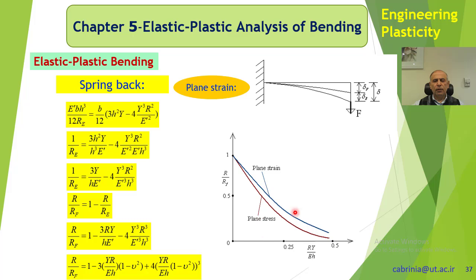Okay, so that is the difference between plane strain and plane stress, but this difference, in my opinion, is not important, because plane stress or plane strain depends on what geometry you have. If you have a geometry where the depth and width are almost near to each other, then you have to use plane stress, and you get this. If they are the other way around, I mean the depth and width are far from each other, then you have to use plane strain.